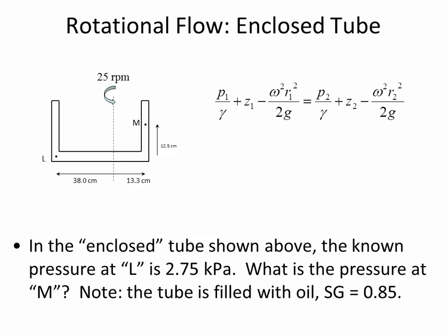All right. So in this case, it never said if these were absolute or gauge pressures. Probably it's gauge because it didn't specify. But if we spun this thing hard enough, we could get the pressure at M to go below atmospheric pressure. And if we were measuring this in absolute terms, we could spin it fast enough that there is a negative gauge pressure, and we could make the liquid pressure at M go below the vapor pressure.